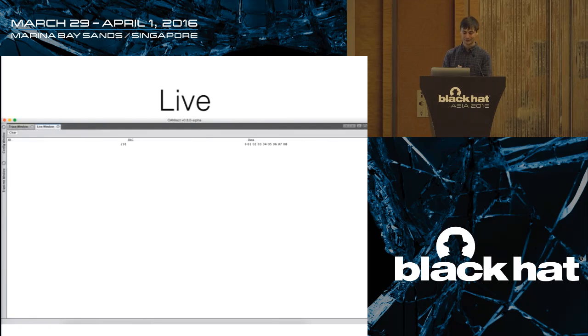The live view is something that is very useful and very simple. Whenever you reverse engineer these CAN signal databases, really what you're looking to do is watch a bunch of messages all at once, change stuff, and see what actually changed in the bus. So we did GPS on a vehicle last week. We got in a car, we waited for a GPS fix, we drove it as north as we could, and we watched all the messages changing, and sure enough, you have something that's updating about once a second, which makes sense for GPS.